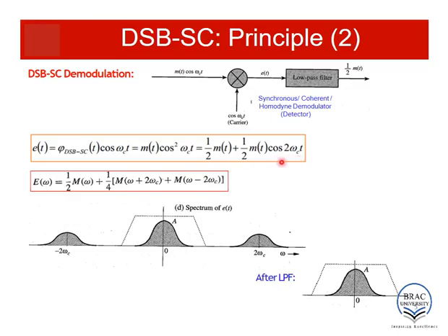There are two parts. One is the message, another one is the modulated signal, but this time the modulation frequency is 2ωc instead of ωc. When we use the low pass filter, as you know, the low pass filter passes all the frequency components less than the ωc frequency. So this component will be passed and this will be blocked. So we will be left with the original message and thus demodulation is done.